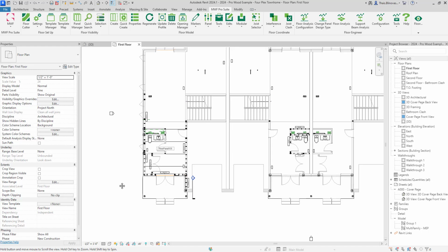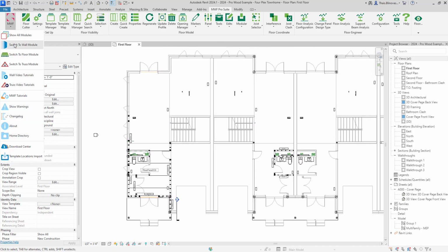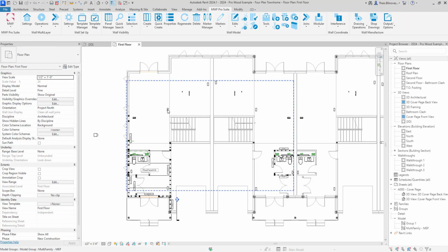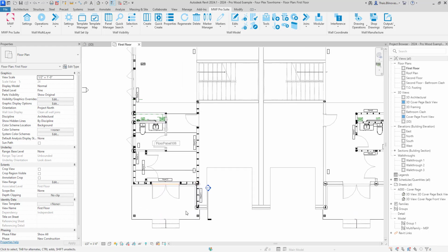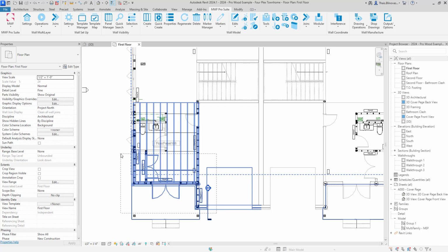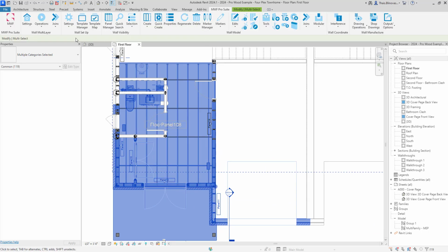And the first feature available is actually a multi-layer feature. So this is for MWF multi-layer panels. And it will give you now the ability of batch selecting all of your panels, and you will be able to easily modify them instead of going one by one. So for example, I'm going to mass select these few panels here. So they are multi-layer panels.